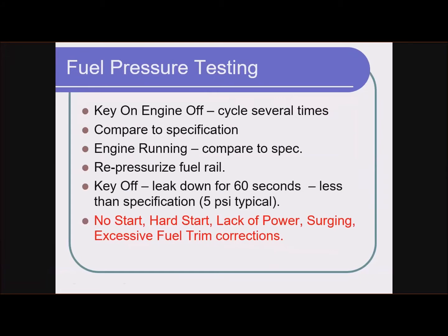So the hard start one, this is the reason for that last test, the key off leak down test. What's supposed to happen when you park a car is a lot of the pressure that's in the fuel rail is supposed to stay there, so that the next time you go to start the car, there's fuel pressure available at the injectors instantaneously. If for some reason the pressure leaves that rail, and we'll talk about what those reasons could be, if the pressure leaks out of that rail